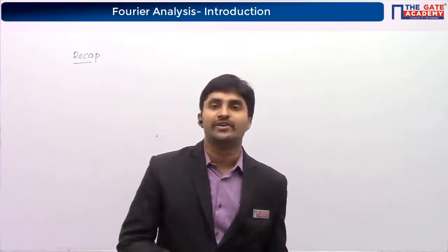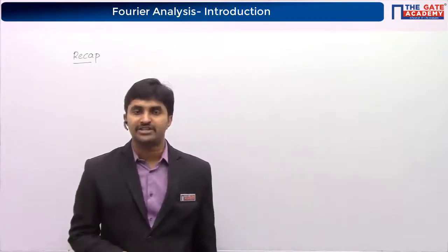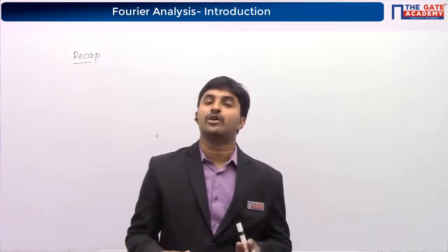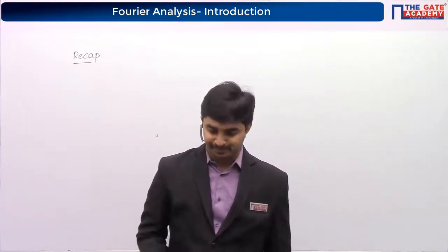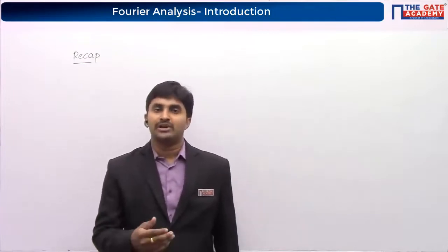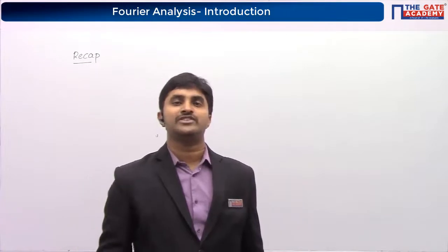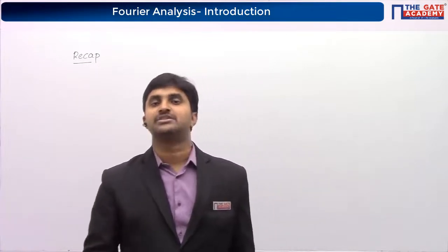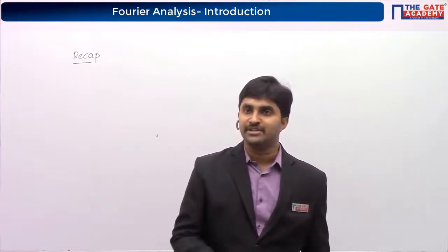And here also we have written the important observations, right, about the lower limit, upper limit, width. So what is going to happen when you're convolving two rectangular pulses of same duration, unequal duration, right? So finally we have discussed about the step response, and also we have discussed about how to tell a particular system is going to be causal, stable from the concept of the impulse response.